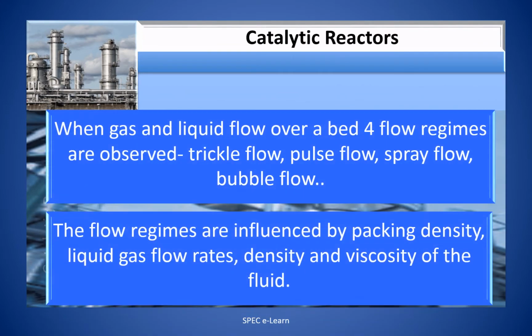Before we move to the next type of reactor technology, let me throw some light on the hydrodynamics of the flow regimes when a liquid and gas flow over a solid surface. When gas and liquid flow over a bed, four flow regimes are usually observed: trickle flow, pulse flow, spray flow, and bubble flow. The flow regimes are influenced by the packing density, liquid and gas flow rates, and density and viscosity of the fluid.